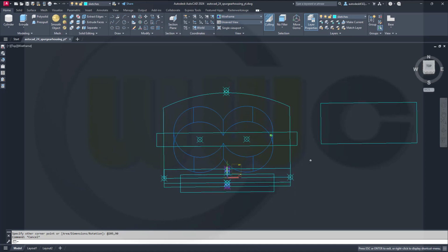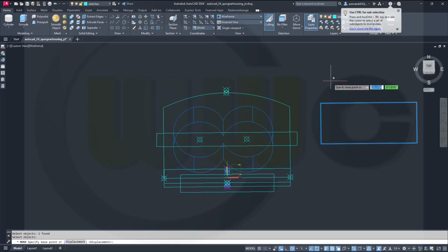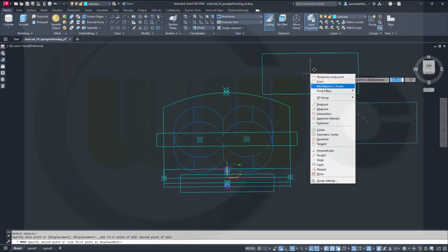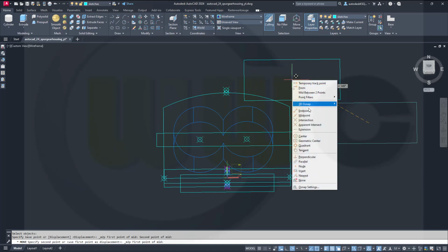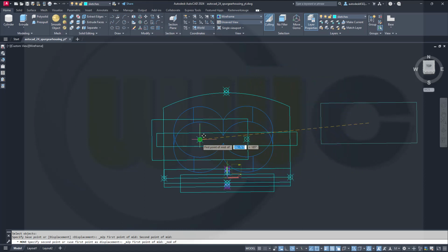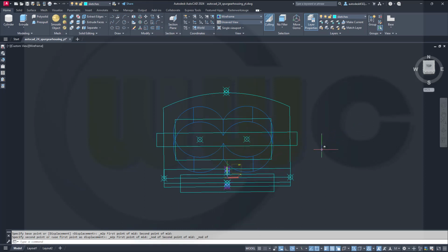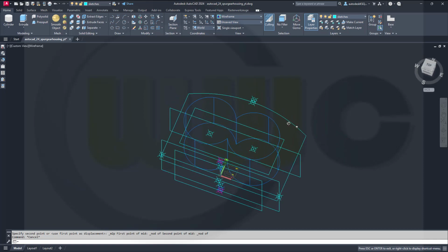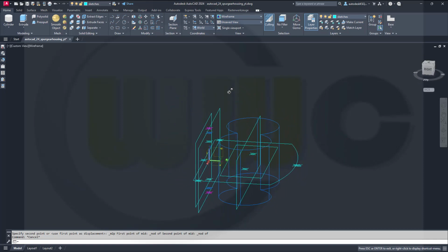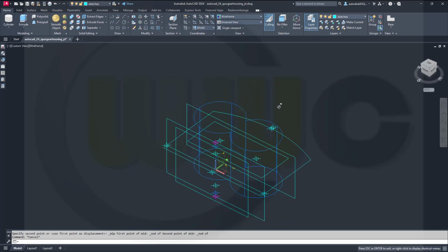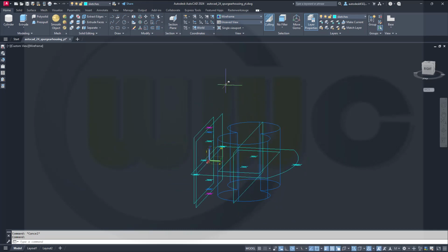And the correct position of this one would be, let's move it, select it, right click, and the base point would be again mid between 2 points, between this point and that point. And this I want to move to, again mid between 2 points, control right click, from that node to this node here. Yeah, that looks okay. Yes, it's okay. Now let's make an extrude.